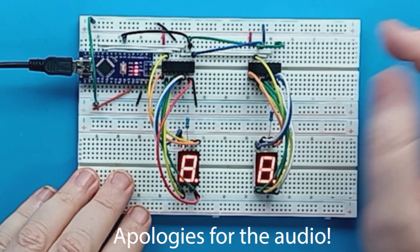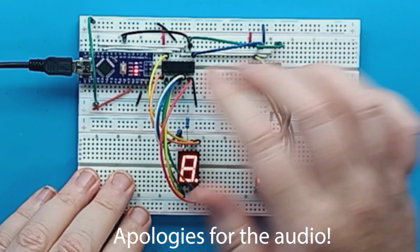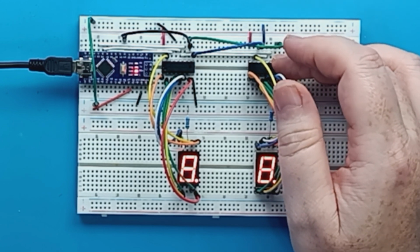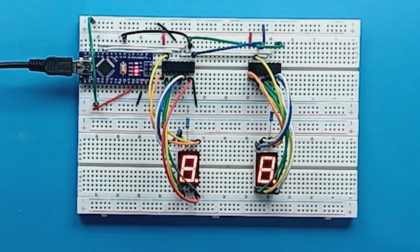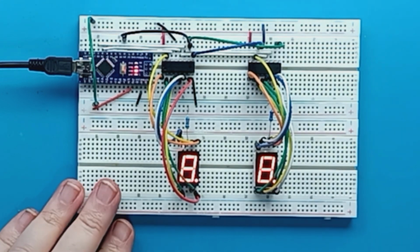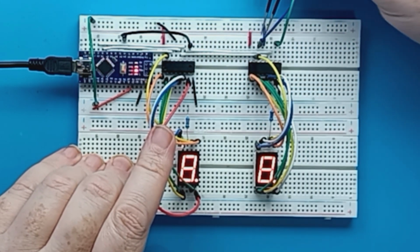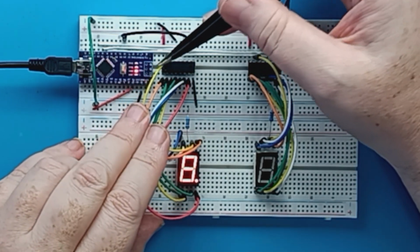Currently, what I've got is 2 of these 74HC595 chips. I'm using the HC variant because the HC variant will work down to 3.3 volts. The other variants may only work down to 5 volts. So it's just something to think of when you go to buy these chips. So what do we have? Well, for the time being, I'm just going to disconnect the second chip and turn it off.